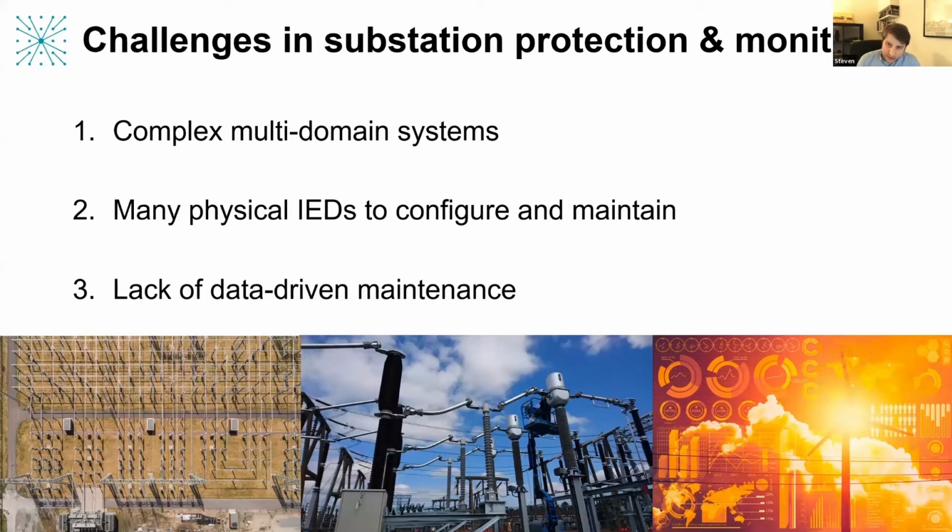So what this means is there's lots of IEDs required in a substation, and each of those requires configuration through the IEC 61850 approach, which is relatively complex, and particularly when you're looking at maintaining those devices over time, there's potentially a lot of engineering effort needed to manage that.